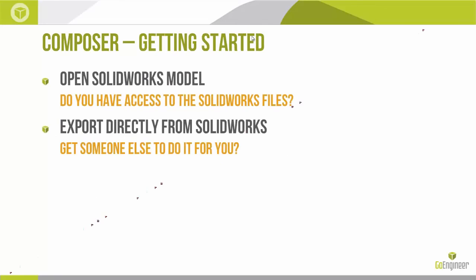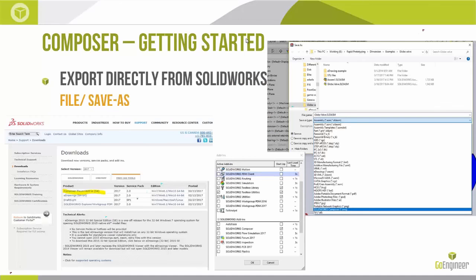Got one more little slide here to go over real quick, and I had this at the beginning at first, but I'm going to go ahead and show it anyway. Getting started, opening up the SOLIDWORKS models inside Composer, we can do that. Exporting from SOLIDWORKS, it kind of depends on whether you want people to have access to the models or if you want to be in control of giving them the Composer files to start with. So, going out to the SOLIDWORKS website, the Composer Player add-in, and then here in SOLIDWORKS, where we can turn the add-in on for SOLIDWORKS Composer.